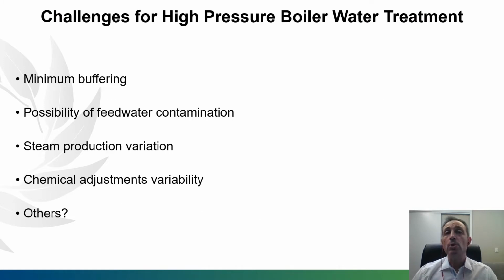So first of all, before we go directly to the controller itself and its features, just a very quick reminder on the most common internal chemical treatment in a boiler, which is based on phosphate. Usually it's congruent phosphate, but some changes can be made as well. And the reason for us to utilize phosphate is that you're gonna add some buffering in the internal water to minimize corrosion.